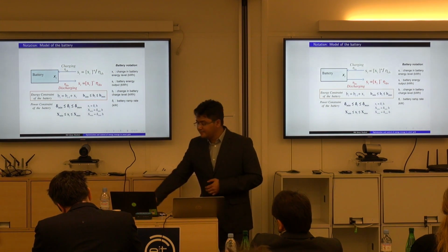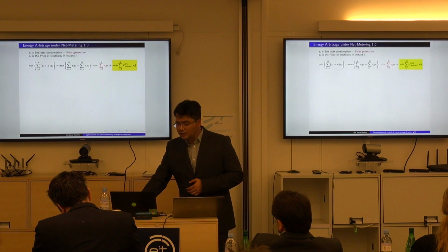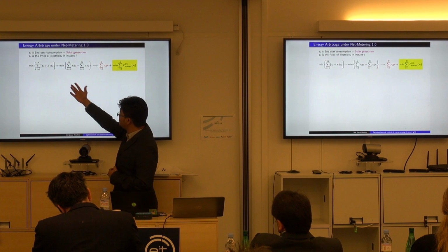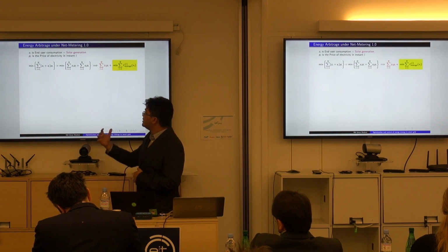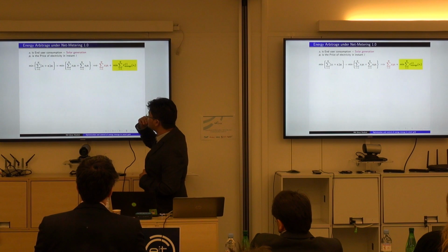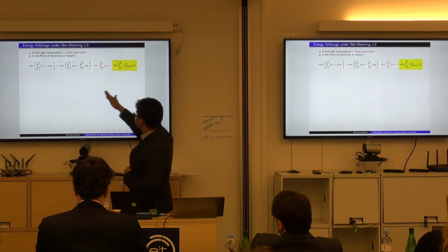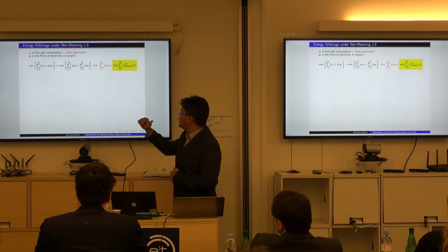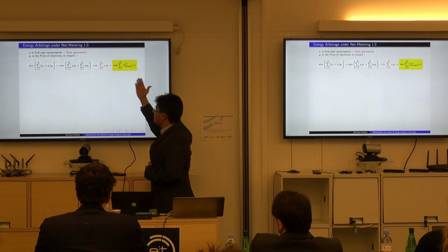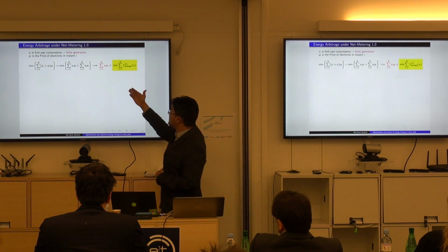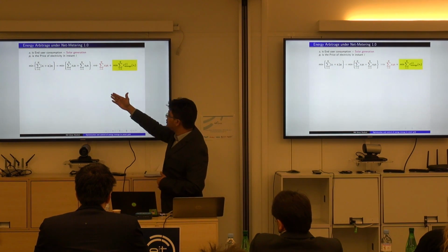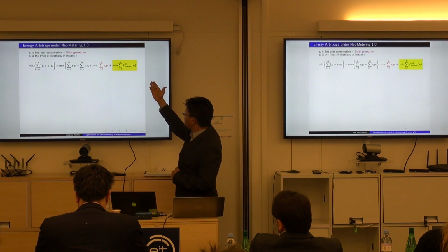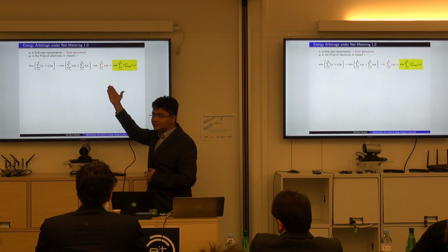As I mentioned, the system consists of a load of end-user consumption and solar generation. This variable is denoted as Zi, and the price of electricity is denoted as Pi. If we expand this optimization problem, we see there is a constant component in the optimization which does not affect my cost function. If we operate under net metering 1.0, in which buying and selling prices are the same, then my cost function is independent of net load and solar generation.